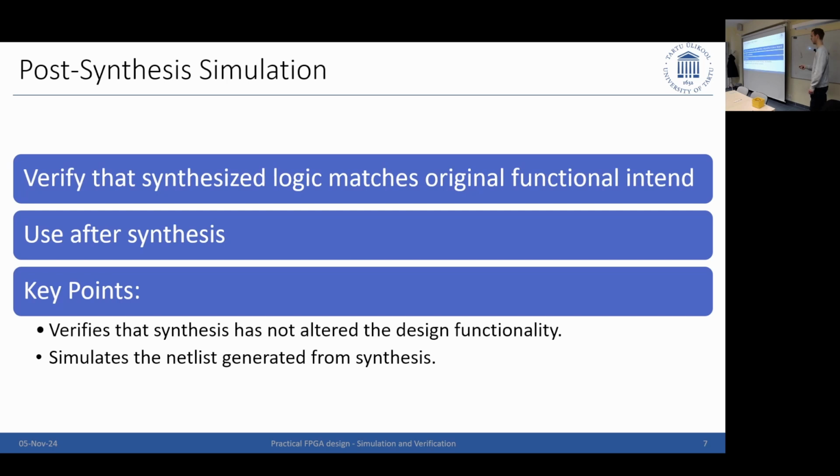This is where automated testing is very strong, because if my behavioral simulation works, I can just run this one automatically, wait for the result, and then move on. Also, I see much better any delay and resource consumption. So after I've done the synthesis, I might run the simulation on this level as well to see how long things take.